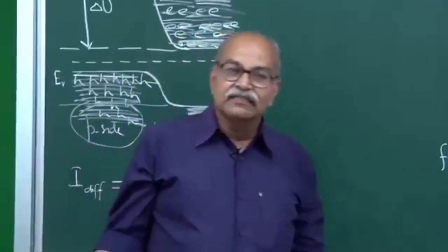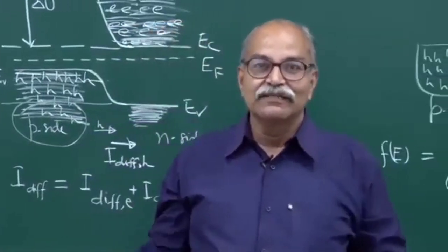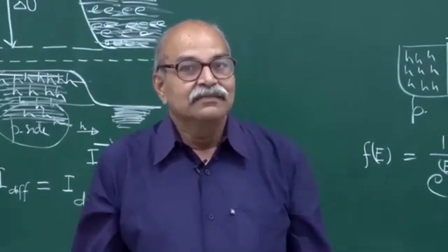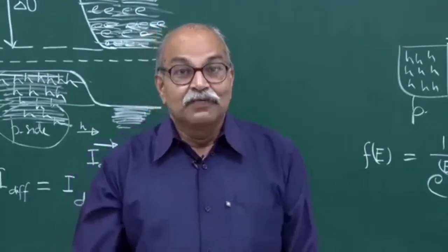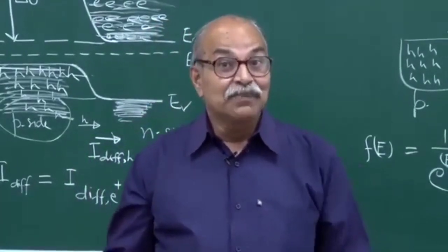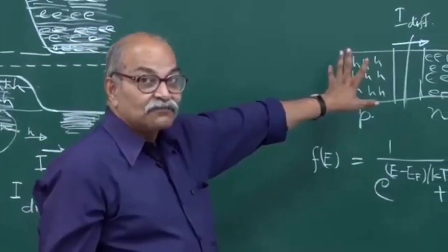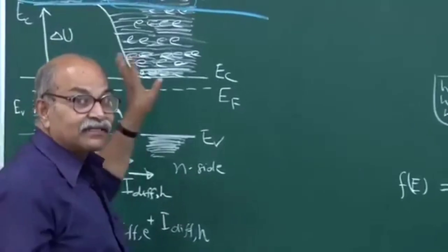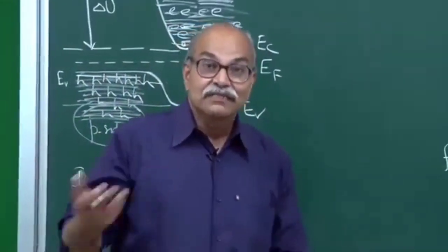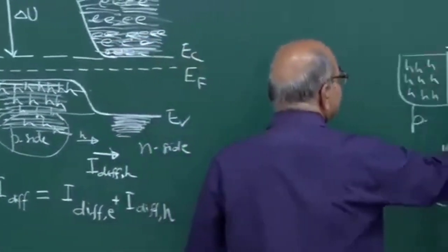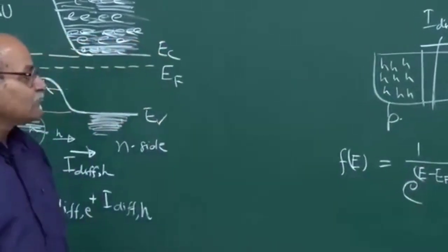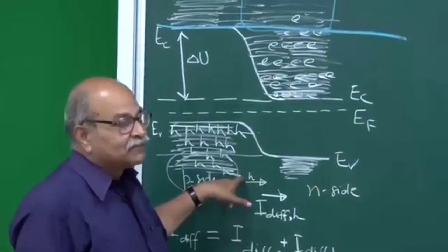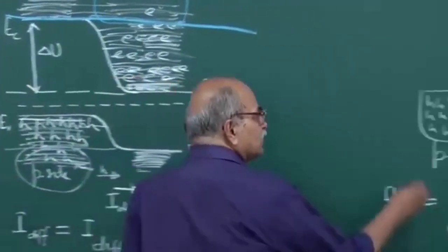But we have not connected this p-n junction to any circuit, no cell, no battery, nothing. It is just lying there on a table. So how can there be a current through this junction, through this system, without charges accumulating at some places? This is all steady state that we are talking of, thermal equilibrium, with all this inbuilt potential difference and energy difference and barriers, after everything is settled. You cannot keep on sending this current without connecting any battery. So what is the other mechanism? We have talked of majority carriers. We have not talked of minority carriers. You also have minority carriers. And how do those minority carriers come?